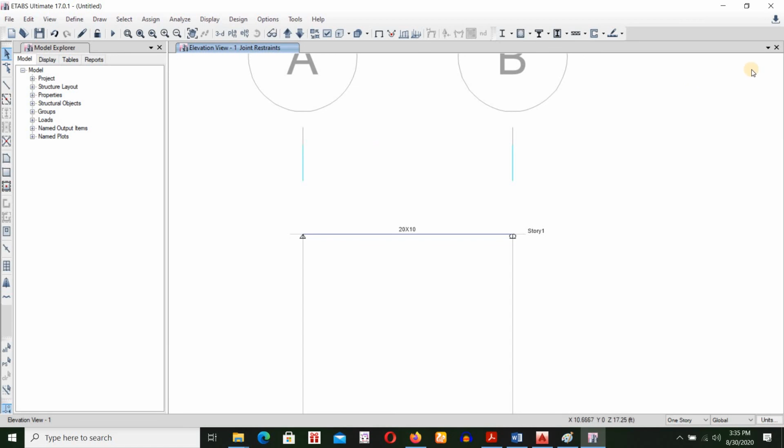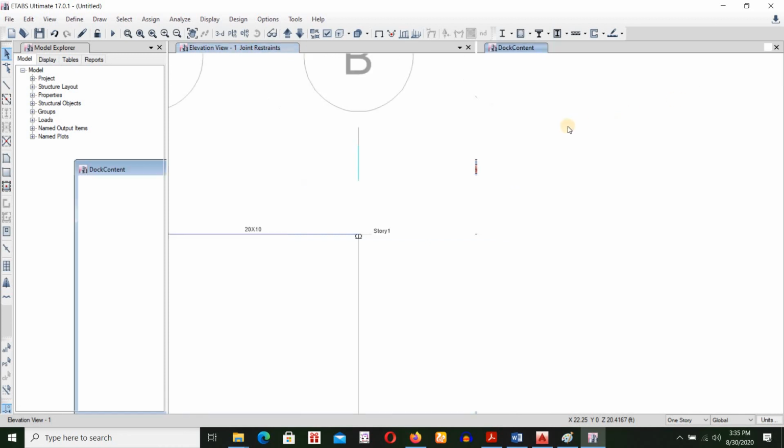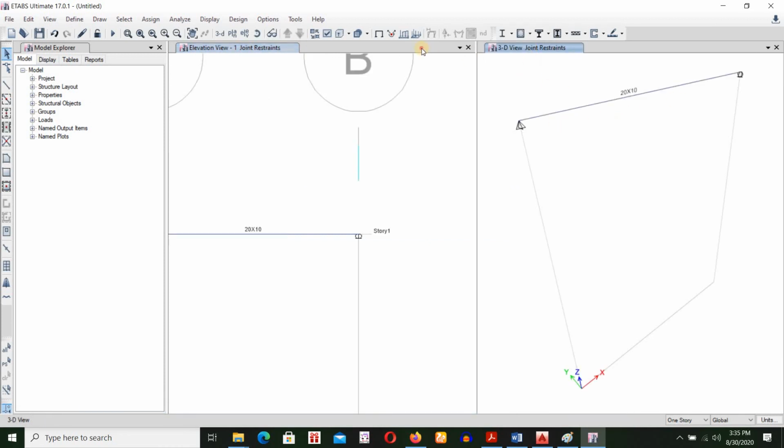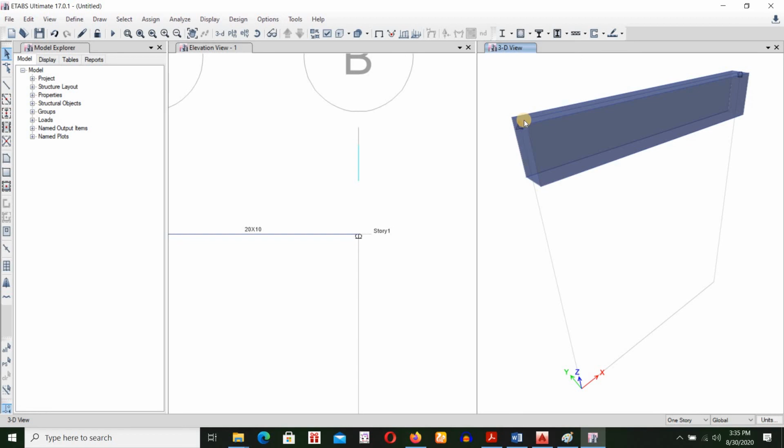If you want to see the 3D now, you'll just go to window list, click on the window list and press on add new window. So the 3D view is here. So we're going to choose the 3D window here, and then we're going to click here the extrude view option. So you can see that it's not extruding, so I'm going to choose the draw option. Then I'm going to choose the mouse option once again, and then I'm going to choose the 3D option and give extrude again. So the beam is extruded.